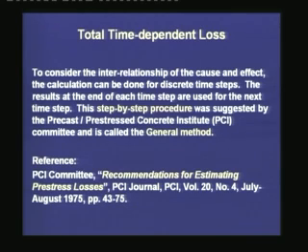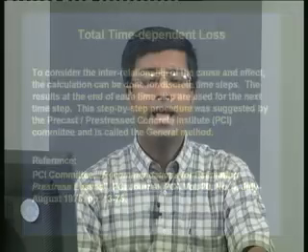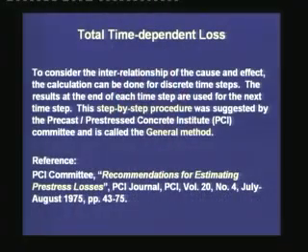But if we want to do the calculations more accurately, we have to use discrete time steps, where we also need to have expressions of creep, shrinkage and relaxation as a function of time. Such expressions are available in the specialized literature or the international codes, with which we can monitor each individual loss with time. The results at the end of each time step are used for the next time step.